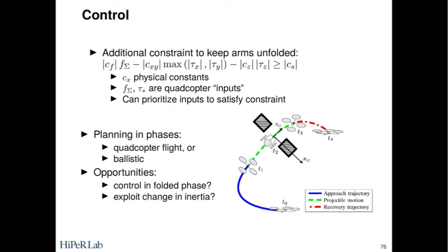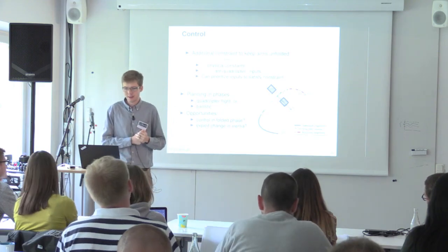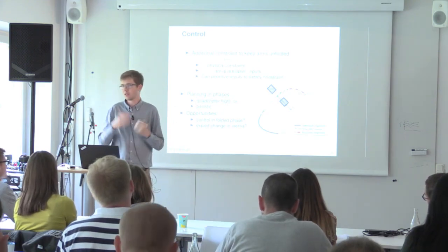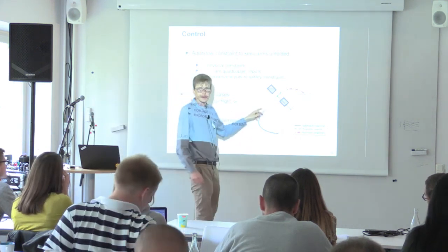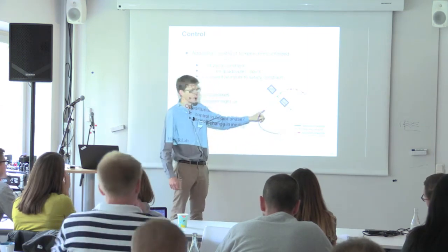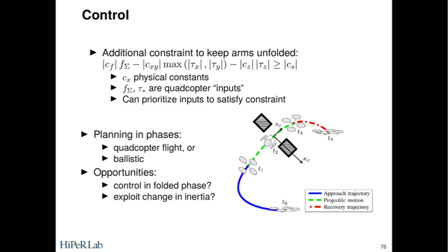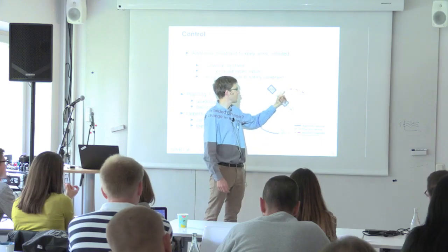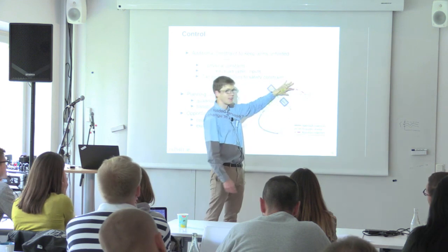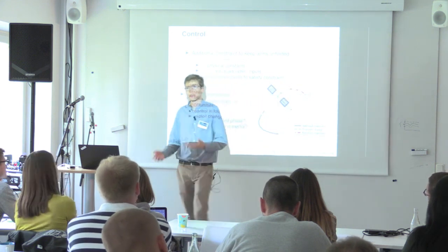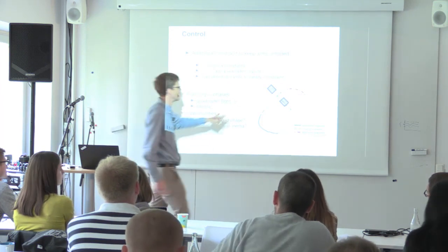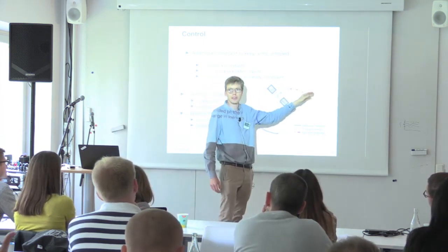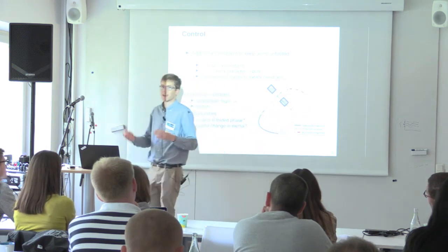It is violent, so there is a lot happening. It's an extremely dynamic thing, but it's not a problem, right? And of course, there would be a strong discontinuity. So if you looked at the control inputs for this first phase, they'll be relatively smooth. Then there'll be a huge discontinuity here. They'll go to 0, of course. And then at this point, there'll be a violent set of inputs in a sense, because your state error will suddenly be quite large. But then it will hopefully, again, if you do your job well, decay smoothly to sort of the hover or whatever the next state is that you're trying to achieve.